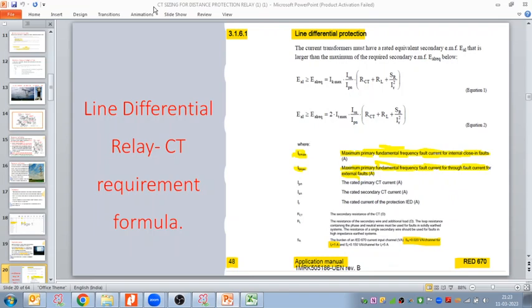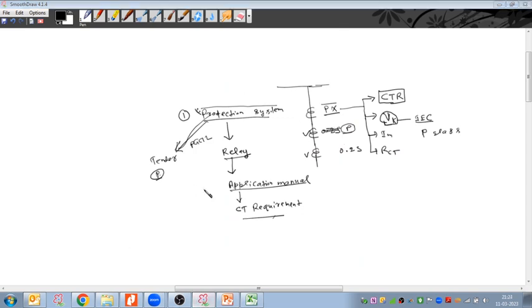Suppose we are doing any kind of solar project in India or anywhere, and the developer doesn't have such a control and protection philosophy. In that case, you can follow that country's grid protection and control philosophy, because whatever you are making, solar or wind, you are going to connect with the grid only. So your protection system should be as per the grid protection system. If the developer has not given any specifications for the control and protection requirement, you can refer to the national grid protection system.